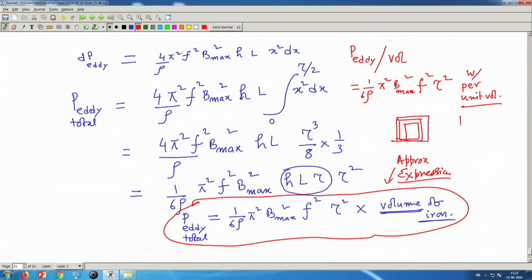Instead of that, the eddy currents will be only confined here, because the next plate is insulated from the other. If you do not use insulated plates, then the story remains the same, the eddy paths will be more. Are you getting? That is why the insulation is necessary.